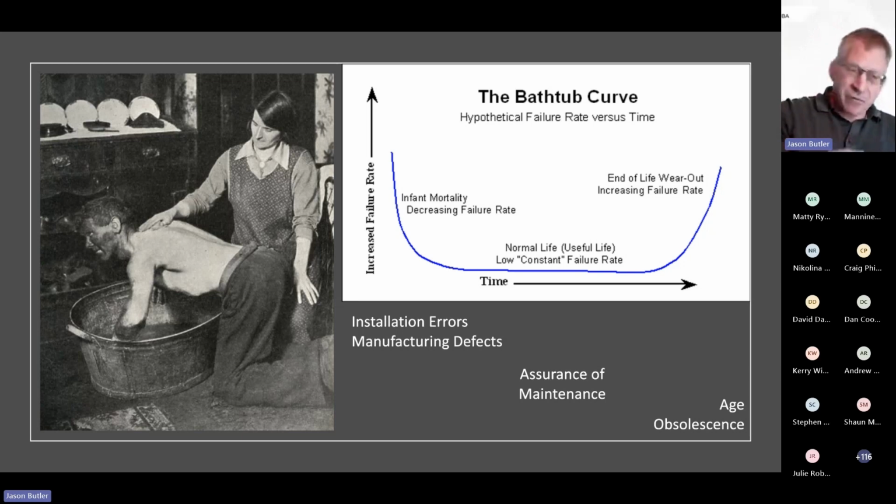So again, if you've got a new switchboard being commissioned, or a new substation, or just something happening inside there, test it. You've got nothing to fear about looking for PD. There shouldn't be PD there. Perhaps do it day 1, day 7, and day 28, just to make sure as it soaks in that you've not got PD early. And then you go to the normal life phase, where you're going in and, in good old MOT style, you're doing a PD survey. Probably once a year, but if it's critical, once every 6 months. There are people I know that do it every month, but that's their choice.